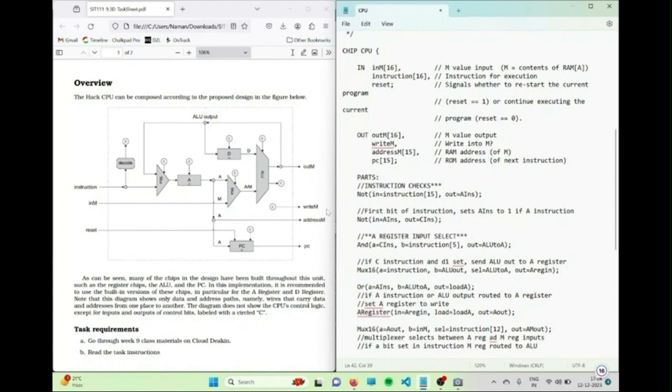In order to do so, the CPU must specify a few things, first including the data that the CPU will write into the data memory, which is stored in outM, and the address of the write operation in the data memory. The output that sends the information to the instruction memory is the PC, which contains the location of the following instruction. The CPU decodes and executes that instruction.